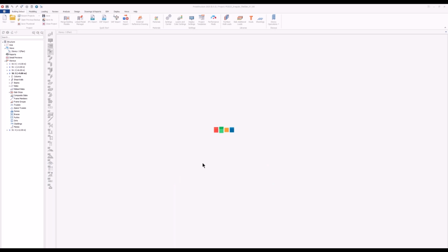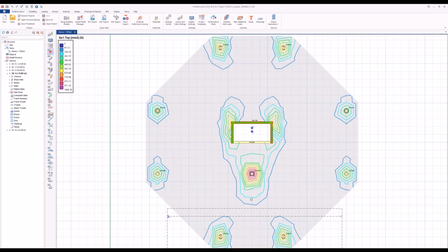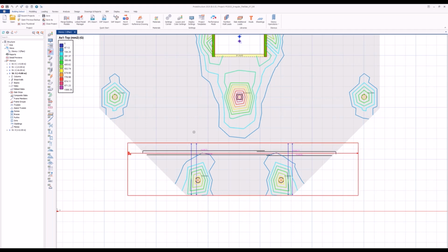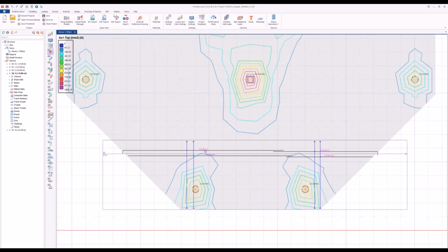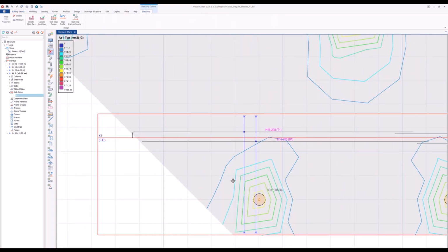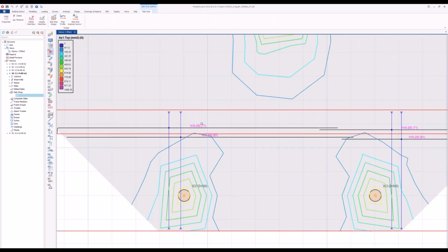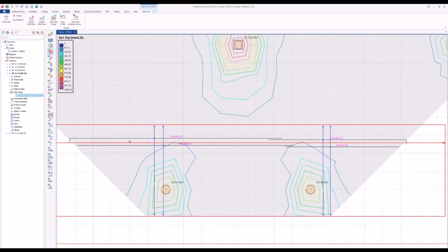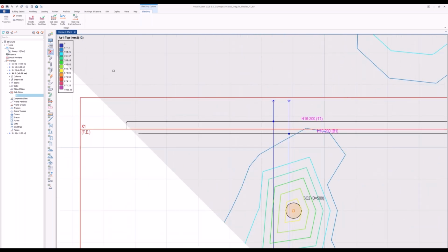So this is again a very important addition in ProtaStructure. Say we have a flat slab here. If we update the steel bar, you will see that this finite element strip, slab strip, has calculated number 16 bars with 200 millimeter spacing. Okay, let's not forget this.